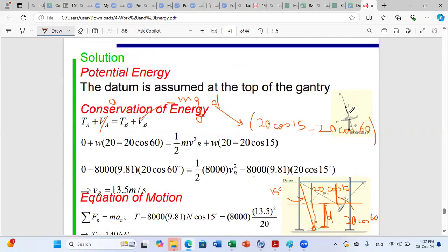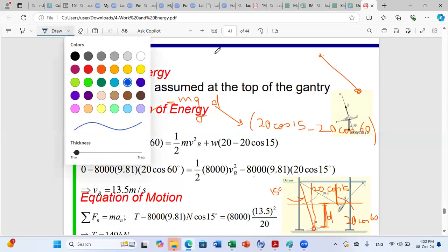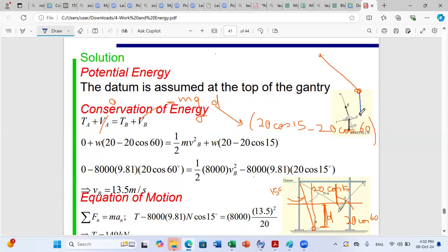So it's along UN. Why along UN? Because if I take my problem, I have a cord, I have my airplane, and it's swinging. What are the forces acting on it? I just have the weight, W, and the tension of the cable, T, acting on the airplane. Because this distance is constant, the path of motion of my airplane is a circular path.